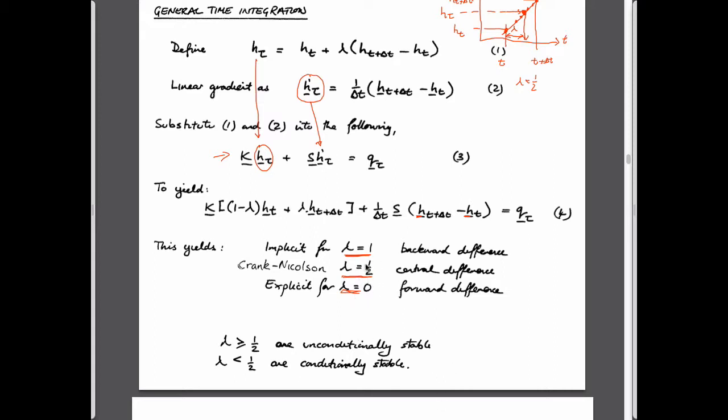And the magnitudes that you get if you write in the middle are actually of higher order accuracy, and you need to do that in some problems. We don't need to do it for the flow problem, but when you look at transport problems, sometimes you have to use central differences. And so this is the other reason for defining this behavior in terms of this lambda term, is that for lambda greater than or equal to half, all of the solution methods are unconditionally stable.